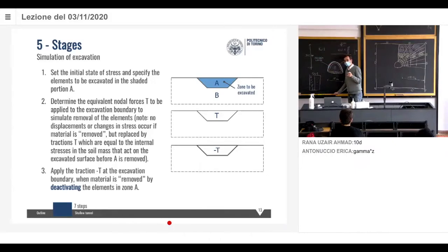Because you may remember in rock mechanics that when you put the primary lining, you need to define the amount of load that the primary lining is going to support. And you do that by looking at the characteristic line of the tunnel. Do you remember that? And the characteristic line of the support, and you find an equilibrium. So this is exactly what we have to do now here. And in order to simulate that, it means playing with the internal pressure inside the tunnel.